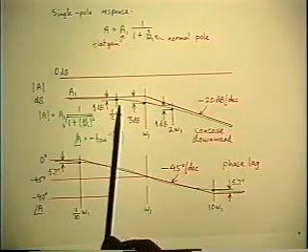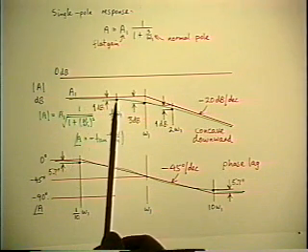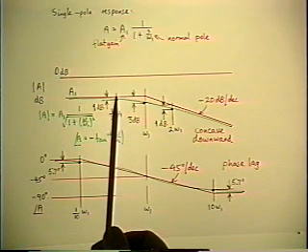So 10% is a good criterion. Anything less than 10%, you forget it, except in special cases. So since 10% converts to about 1 dB, 1 dB is a good place to choose on this picture to say this is the frequency at which the actual magnitude function has begun to deviate significantly from the straight line asymptote.